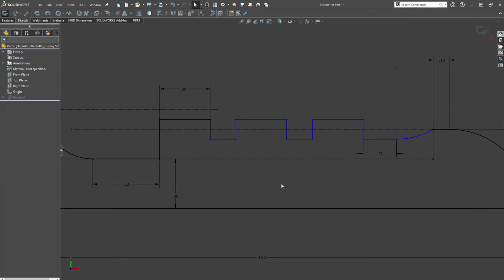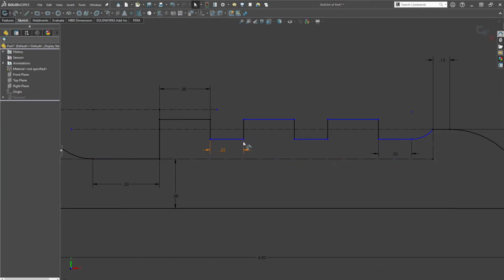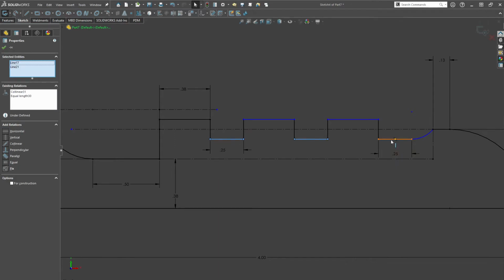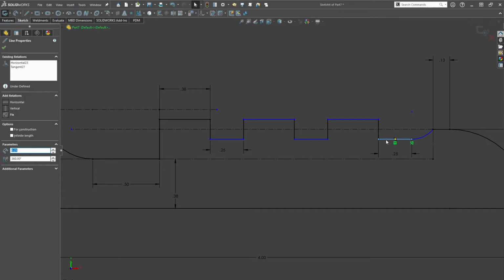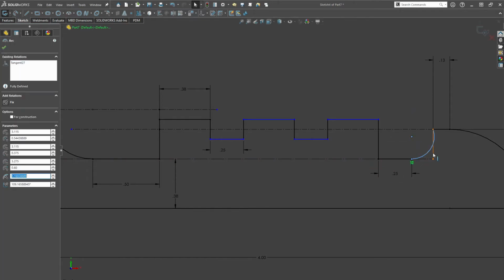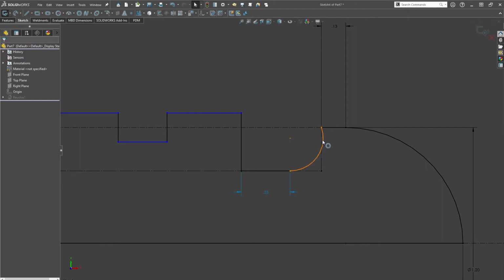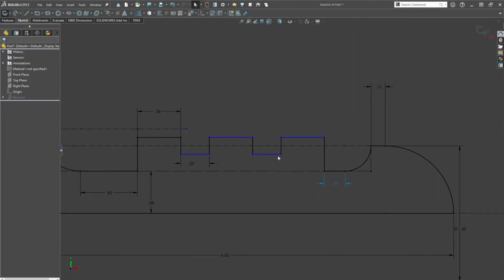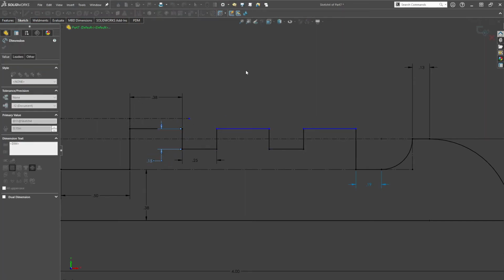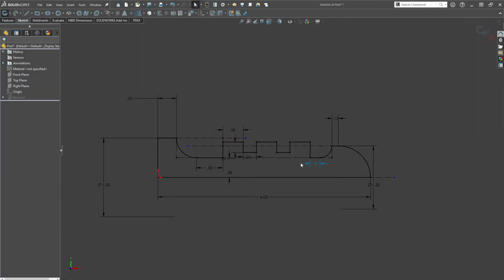In the same vein, we're going to make those equal, and we're going to set that distance to 1/4 inch. And now we just need to set this diameter, which again, I'm going to make collinear with that diameter. Actually, I want this diameter to be lower. We'll put this one back there again. And I want you to be tangent. There we go. And for this diameter, let's do the depth. So we'll go 0.2 for the depth. Oh, and these 3 should be collinear as well.